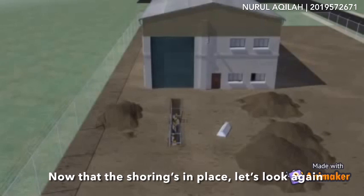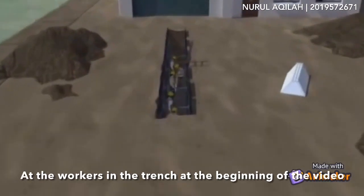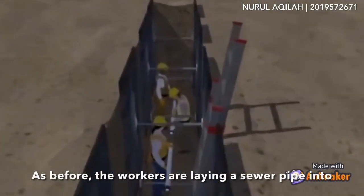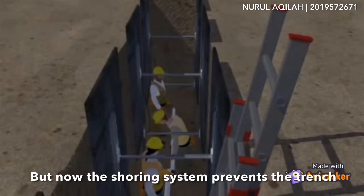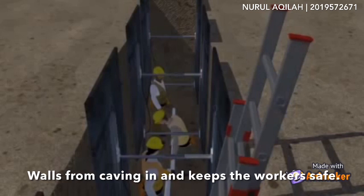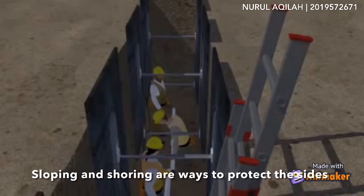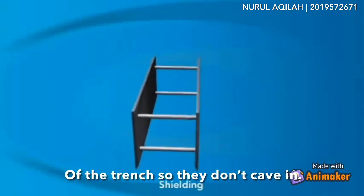Now with the shoring in place, let's look again at the workers in the trench at the beginning of the video. As before, the workers are laying a sewer pipe into the bottom of the trench, but now the shoring system prevents the trench walls from caving in and keeps the workers safe. Sloping and shoring are ways to protect the sides of the trench so they don't cave in.